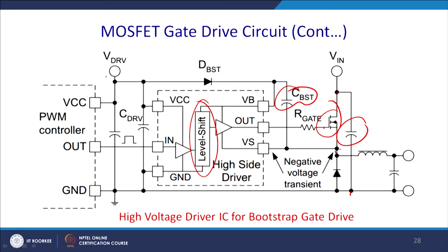So due to this capacitor, there will be a voltage across this point and this point, and this voltage maintains the higher driver voltage than this VIN. The requirement that the gate voltage be a little higher than the source voltage is fulfilled, and this is called bootstrapping. It is required for switching on the upper MOSFET in an inverter or any application where, when you turn these devices on, the source takes the forward voltage, which is more than the gate voltage of the source.